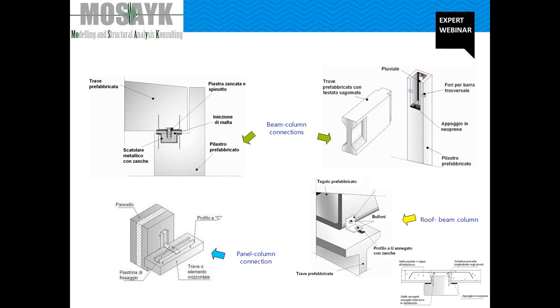Connection between saddle beam and the top of the column in one-story structures means dry connection with use of one transversal ungrouted steel bar on the top left of the slide, diameter 24-30 millimeters, tightened with nut and washer, or a maximum of 2 grouted vertical steel pins.